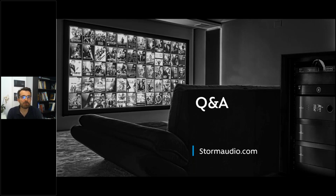You know, it's very similar to when you have different speaker types. To maintain the timbre balance is not simple. So in the same way, if you have subwoofers that are capable in the same frequency range with the same SPL, you can make sure that the system can use them evenly, and you provide then a very homogeneous sound reproduction. So that's a recommendation, I would say, to use similar subwoofers. But if you cannot, then make sure that your adjustments follow your subwoofer requirements. So you will have to split your subs and adjust them independently.